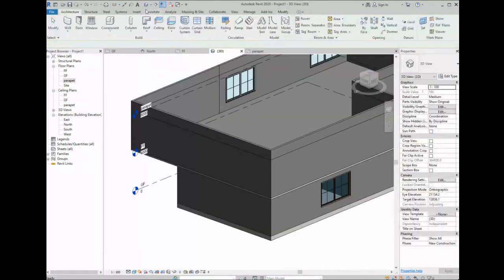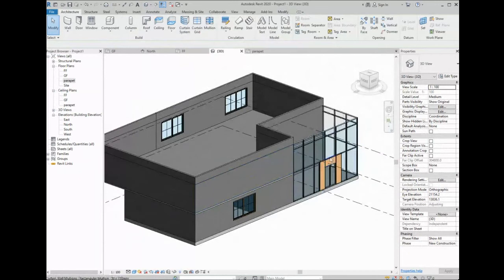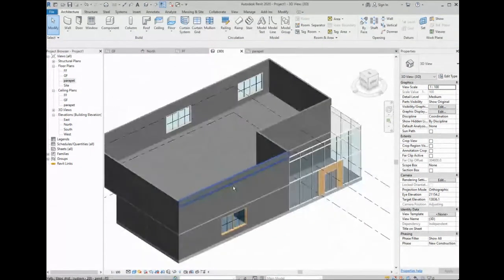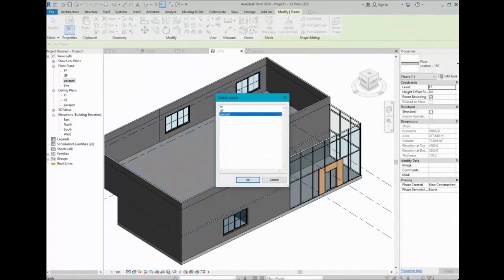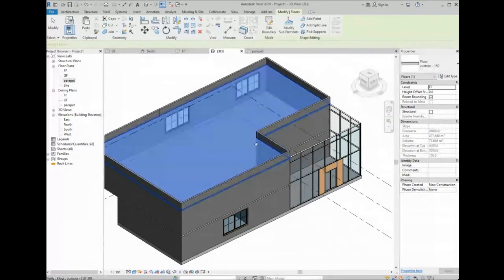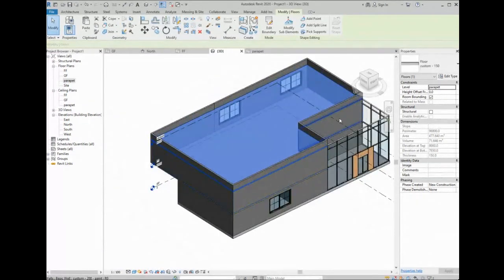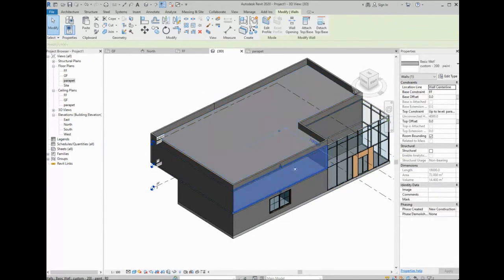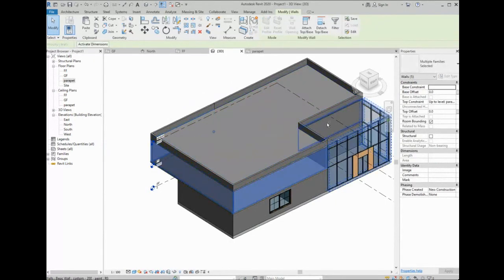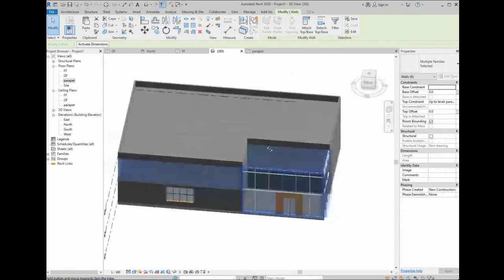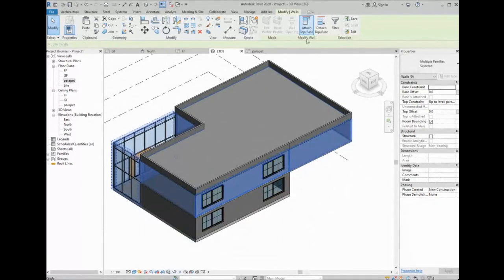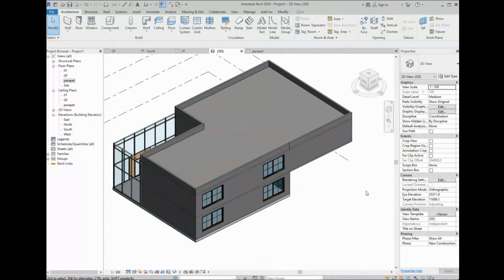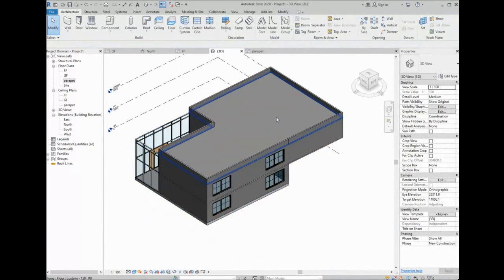Yes, and then I will go to 3D and check what happened. So now I have flooring. Select this flooring and then go to copy, paste to parapet level. Okay, again, I will select all the walls. I'll just make sure that I select all of them. Attach to this one. Okay, so now everything is okay. This is if I just want to add it as a slab.